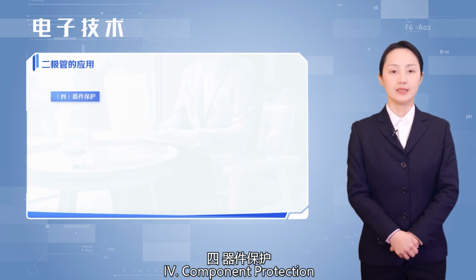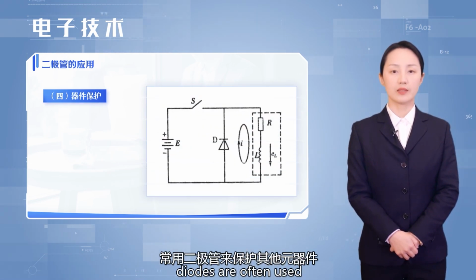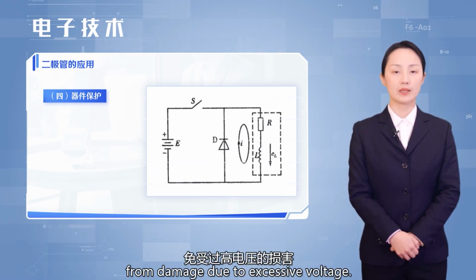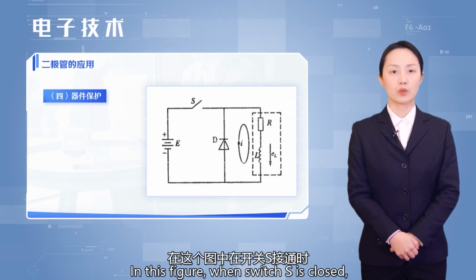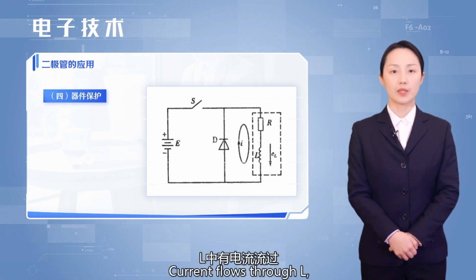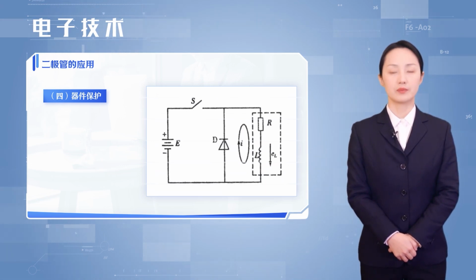Component protection. In electronic circuits, diodes are often used to protect other components from damage due to excessive voltage. In this figure, when switch S is closed, power supply E supplies power to the coil. Current flows through L, storing magnetic energy.